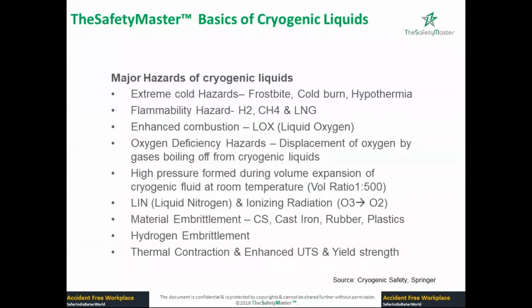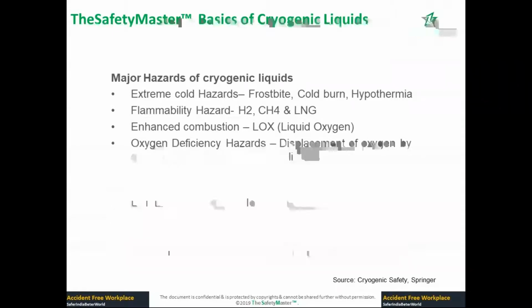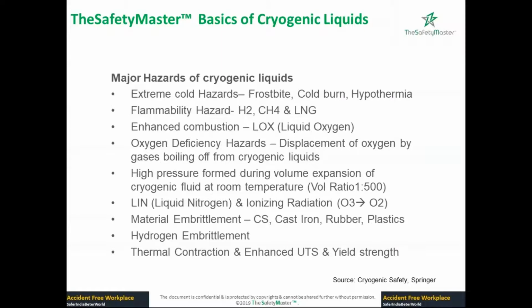Oxygen is not a flammable material, but the hazards come as soon as there is an ignition source. And even if you pour liquid hydrogen on a material, it can immediately catch fire if there's an ignition source. So oxygen is a very peculiar gas, and it has its hazards, both flammability and oxygen enrichment and deficiency hazard, which I will take up specifically during this webinar.